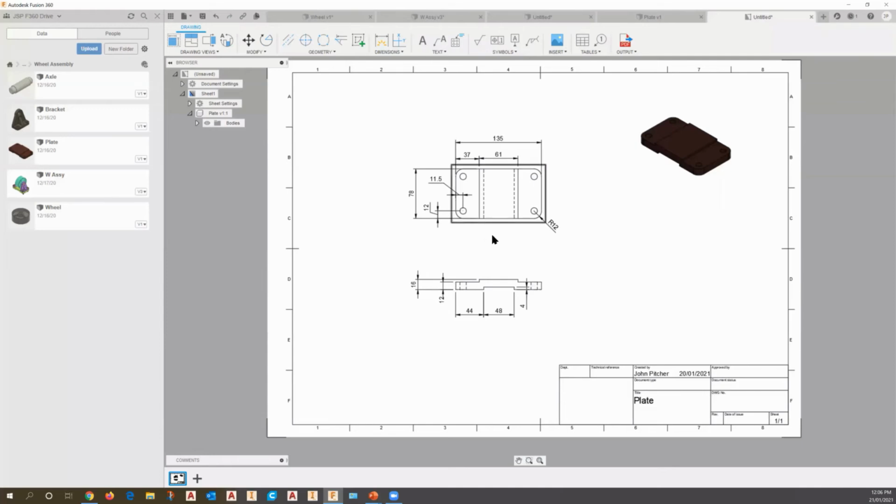Now look, really there's no set order that we need to create things in this sense, but what we're going to do in this little example now is draw a rectangle on the face to create this little 4 mil cutout here. So it's 48 millimeters wide and 44 millimeters in from one end. We're going to create a little cutout in the bottom, so this little shoulder underneath here, if you like. We're going to create that little cutout as our next step.